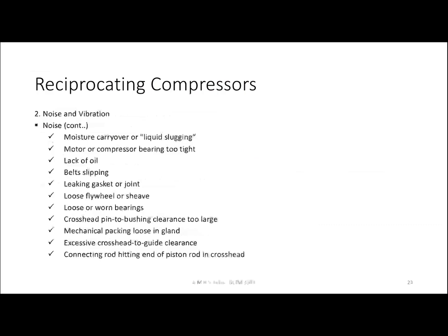Okay, and then another cause for high noise in a compressor can be moisture carryover or liquid slugging. It can be caused by a motor or compressor bearing that is too hot. It can also be caused by a lack of lubricant oil, or belt slipping.